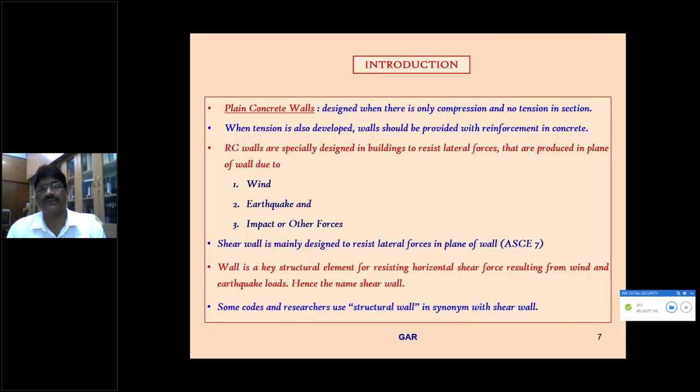Now, that is just background. You can design the system with only beams and columns at a joint. It's a frame system. You can also combine walls, because it is the force which is destabilizing the whole building. The destabilizing effect can be counteracted by providing a lateral resisting system. Either you can design very strong columns, with more columns appropriately located, or along with the columns you can also think about providing wall elements, depending on the planning of the columns and other requirements.